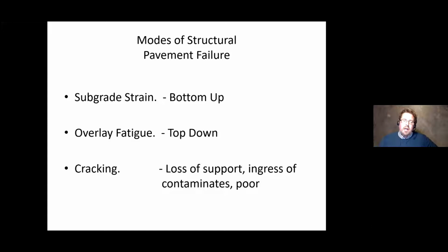And then cracking. Cracking is a curious animal in terms of its occurrence. It can indicate a range of things, like transverse and longitudinal cracking can be a sign of lateral settlement across, or differential settlement across a bog, but clusters of it can be signs of joints in concrete. So it's a matter of looking at your environment and seeing what's happening as a result, what could be causing this cracking.